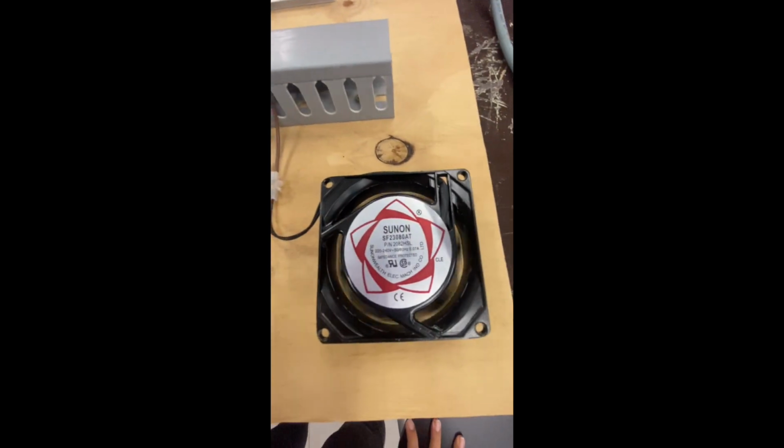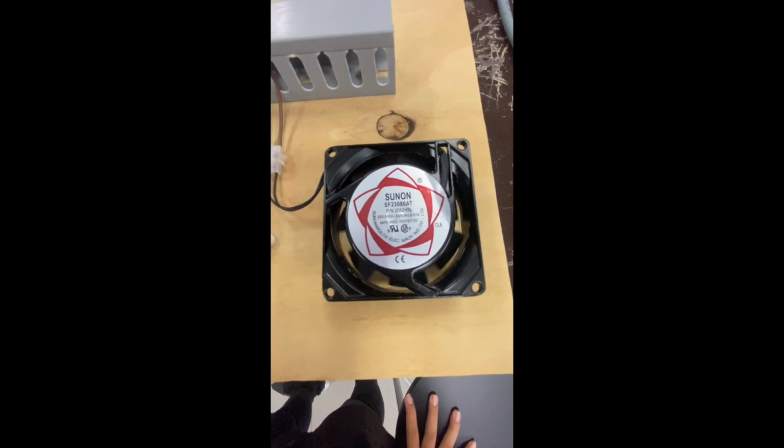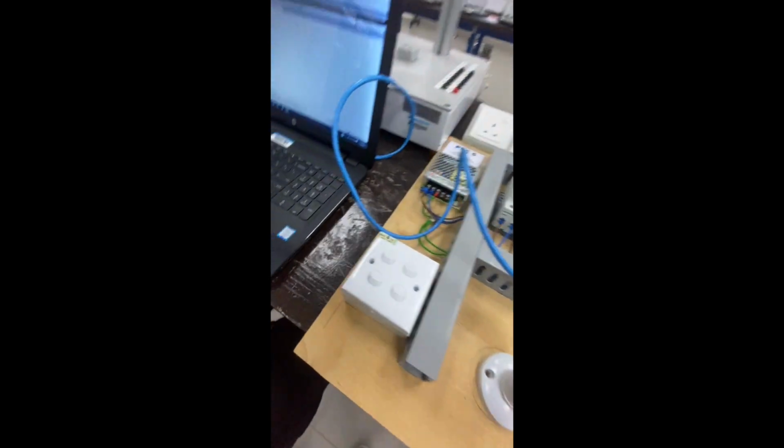So this is the ladder diagram for task 2B. We already connected the lamp, which is Q1, to the output of the timer on delay. Hence, the lamp will turn on immediately, while the buzzer and the fan, which are Q2 and Q3, are connected to the input timer on delay. So they will turn on 5 seconds after push button 1 is pressed.